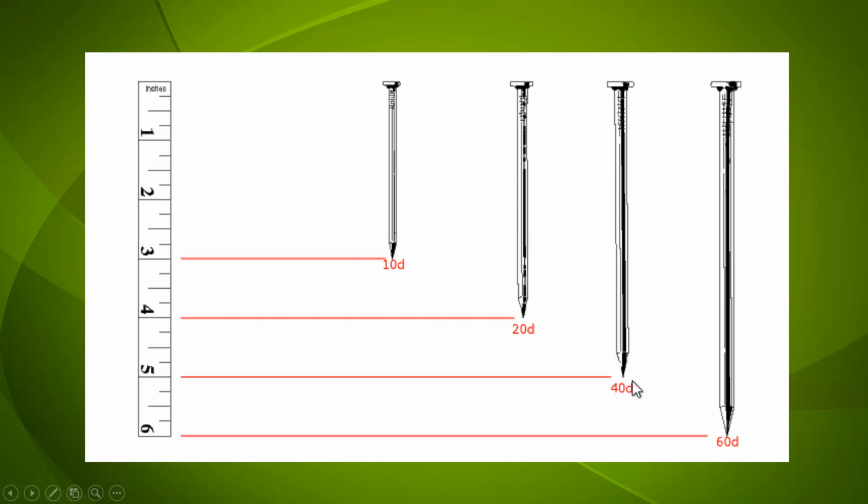inch, and so on. So that means when I create a block called nail, the default way I can create only one block. So that means if I want to create these 4 nails, I have to create 4 different blocks. But at times I don't need all the 4 different blocks. So I can use a dynamic block to toggle between different sizes of the nail itself. So now let's see this example and get to know dynamic block in much more detail.